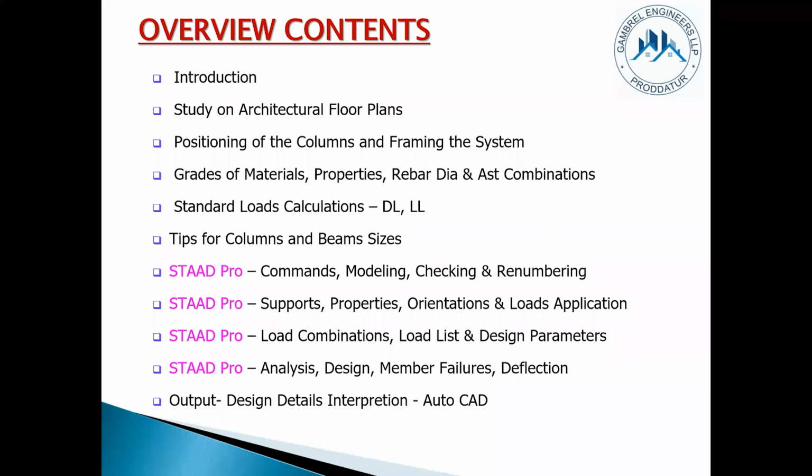You'll be given the architectural plan mentioning the column positions, column orientations and everything, including column sizes. You'll be given the grade of material also, whether it is M20 or M25, and everything is given to you, which was supposed to be done by you. So you take this information and start creating the same thing: create a node, create a column, then use the beam creation options and create members, plates, and add everything.